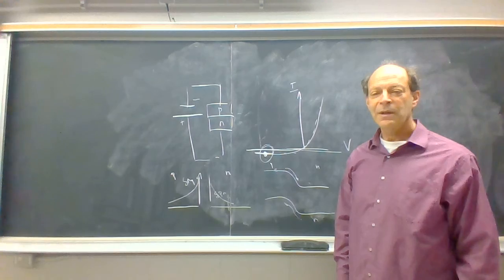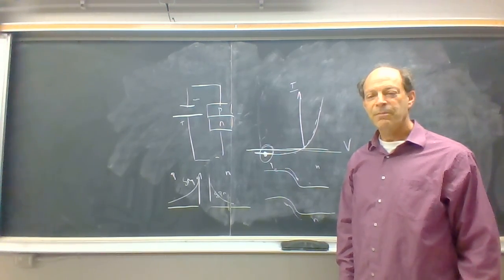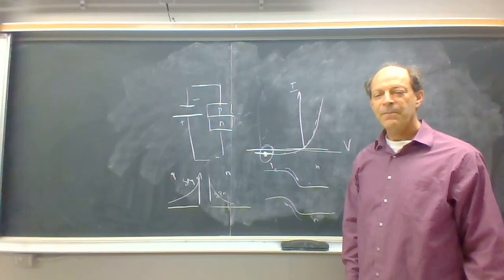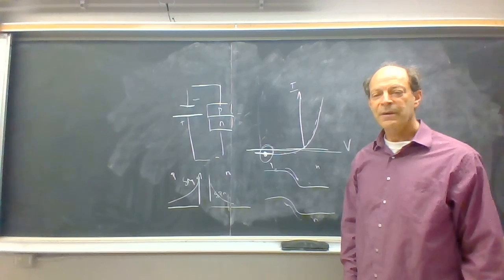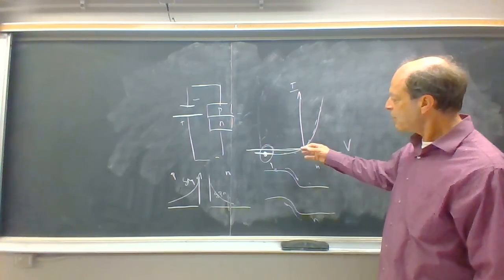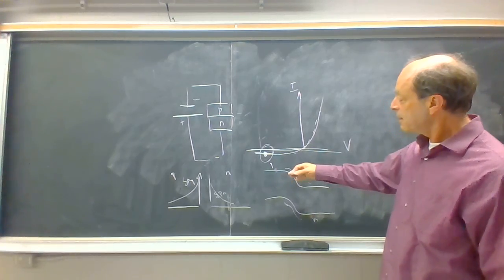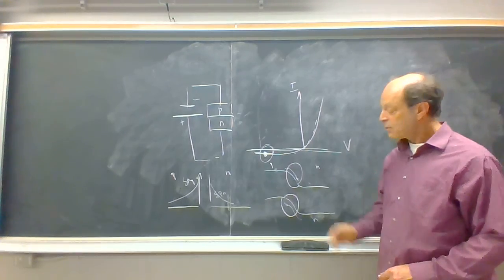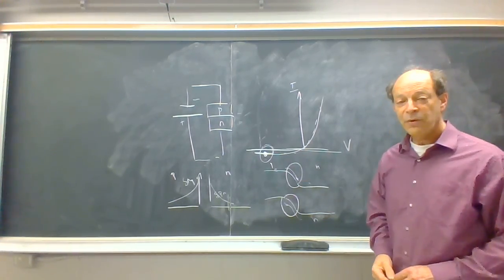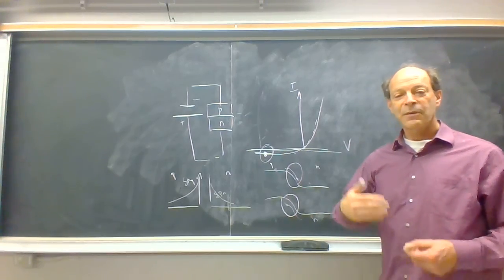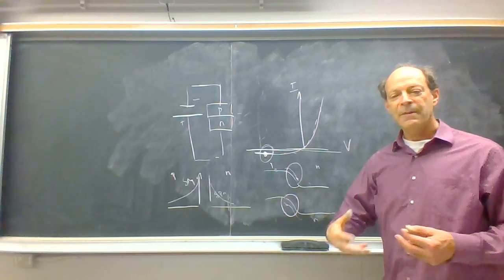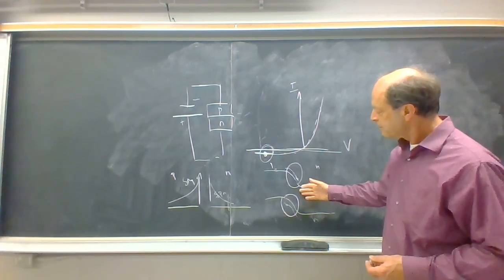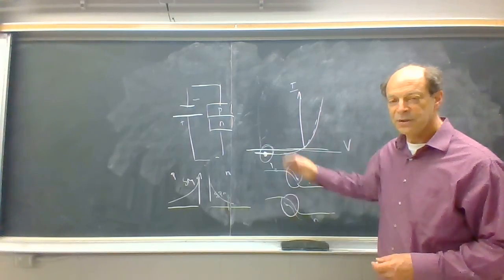But we can also do it electrically, and that's what you do in a bipolar junction transistor: you electrically increase the reverse saturation current by increasing the carrier concentration in either the conduction band or the valence band, so that you get a lot more carriers during reverse bias, and the increased number of carriers is controllable. If you can control that increased number of carriers, then you can increase that reverse saturation current.